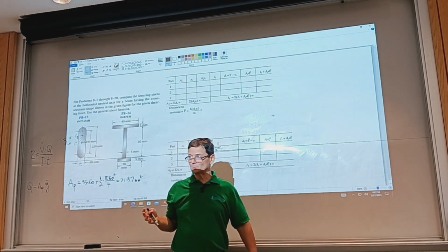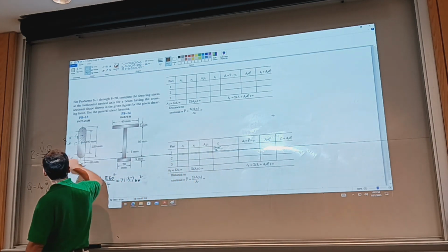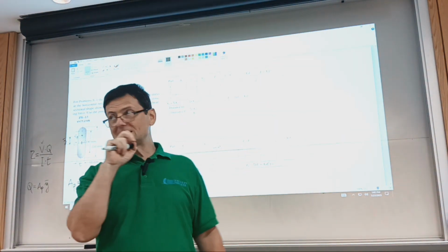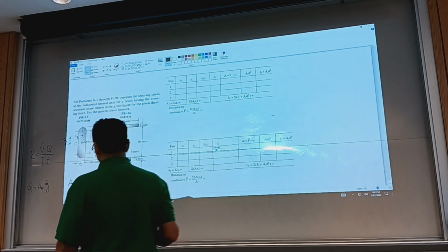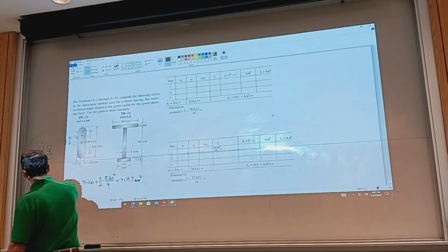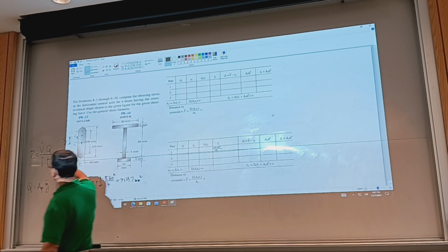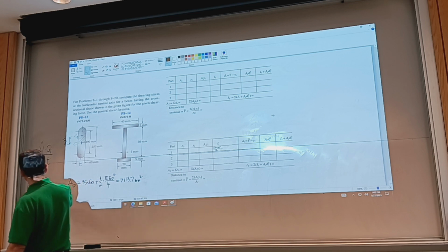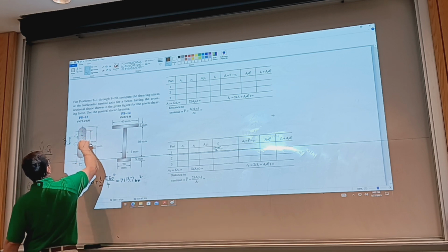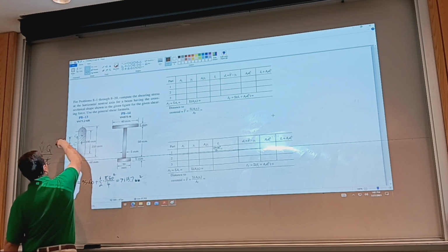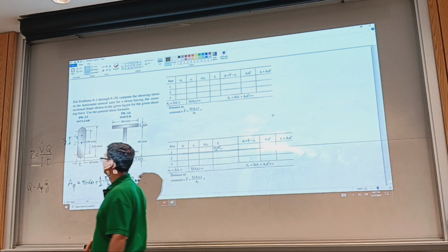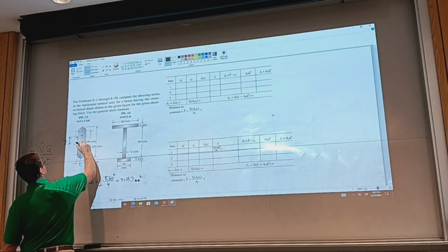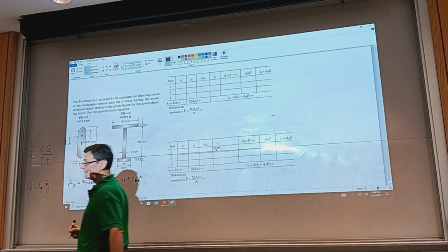And this first problem requires us to use the general formula to evaluate the shear stress at the centroid. And in most practical cases, it's where the shear stress due to shear force is max. We wrote the stated equation for the first moment of area. This is the partial area, which would be the area above, although we can take the one below, of the horizontal plane of interest where we want to evaluate shear. And this is the distance from the centroid of the entire section to the centroid of the partial area, right?